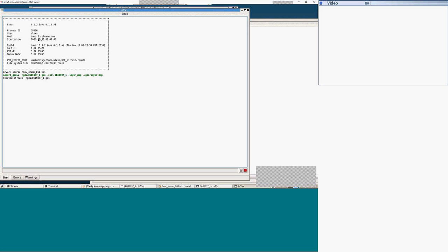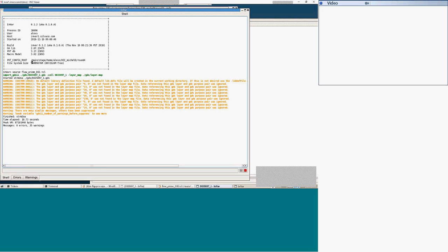So this is also important. The header, when you start the tool, you have on the second line from the bottom this PVT configured variable, and it tells where it points to. So OpenAccess is a file-based system, so it requires some disk space to create temporary data.